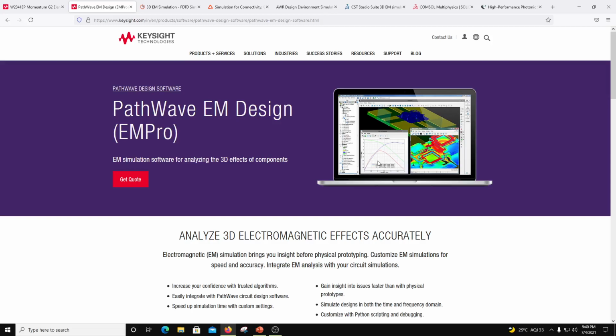And by default, the edge on these meshes should be at least 1/10 of the wavelength. So with meshing, you have some control to intervene. You can decide the meshing in different parts of the geometry, but it is highly automated and you can rely on the results of an automated mesh, right? You do not have to insert your own settings for the meshing. Okay, so that's what the finite volume method is doing.